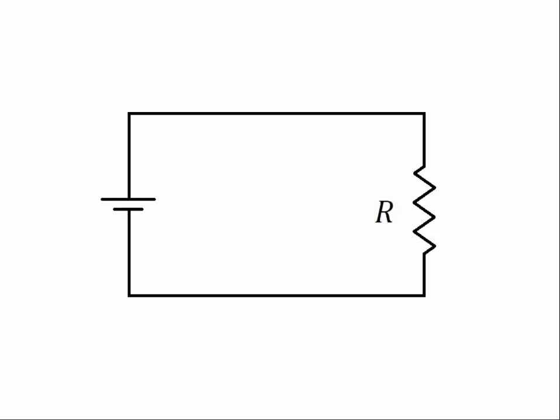So this is what Ohm's law tells you. So here's Ohm's law, V equals IR. It relates the voltage across a resistor to the current through it and its resistance. And you're going to be using this over and over in the lab exercise. So knowing the voltage of this voltage source and knowing the resistance of the resistor, you should be able to calculate the current through it.